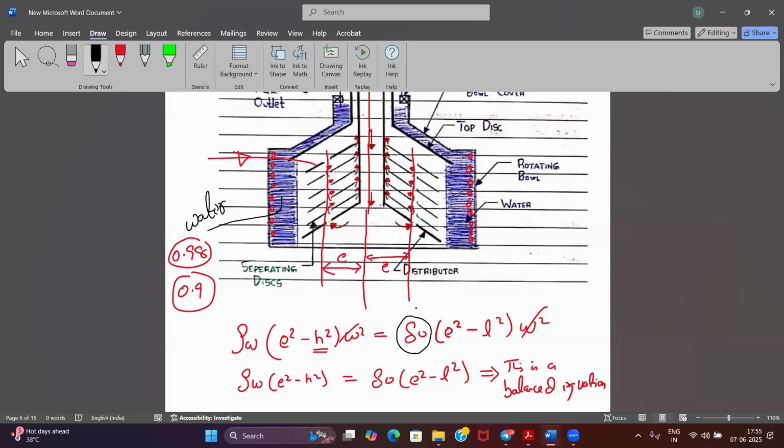I discussed this with one of my students days back. In the previous shift it happened to me that all four purifiers were overflowing, and he did not even check the density of the oil. You should never overhaul all the purifiers together with everything open. He came to me saying, sir, all purifiers are overflowing, and I said if all are overflowing it is a common problem, you should not have overhauled it. I saw the density is more than one. It is written in the manuals also: if the density is more than one, go for clarification mode.